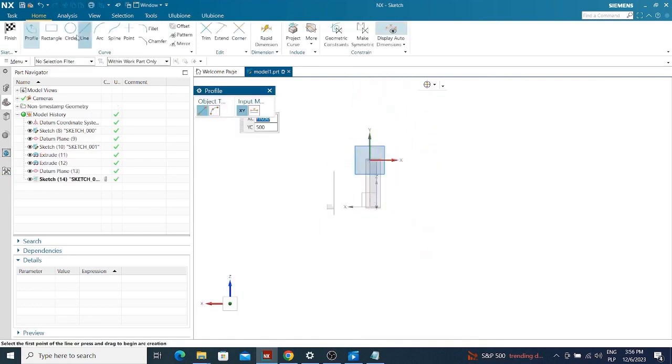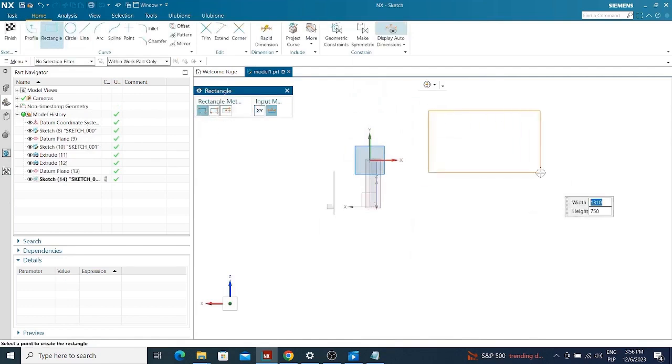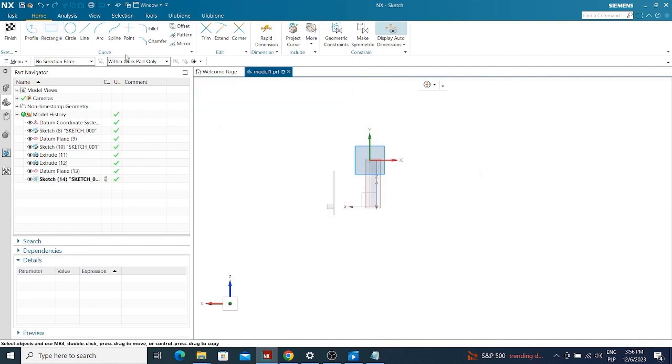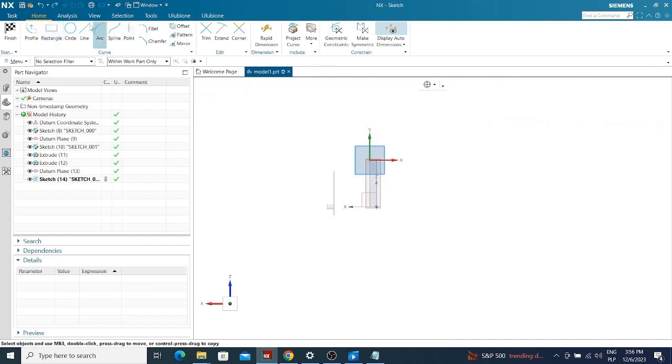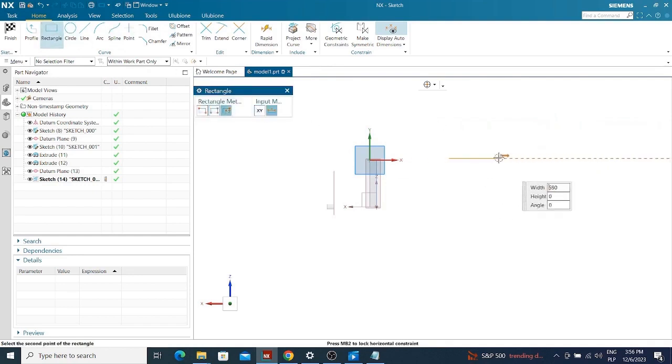I choose a rectangle, and I have several different options for making rectangles. For example, the first method is to mark 2 points on the diagonal, then return to the control panel to confirm the selection. The second method is to select 3 points, ensuring they form a triangle. The third method involves first marking the center point, then clicking or entering in the window, such as a width of 1000 units, a height of 200 units, and an angle which can be either 0 degrees or 90 degrees. Let's make it 90 degrees for this example.